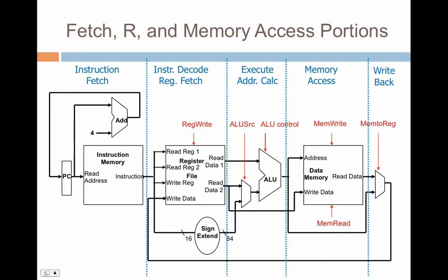the instruction fetch, where we fetch the instruction, then decode and register fetch. We find out what the instruction is so that we can set the control bits, and we fetch data from the register file. We execute in the ALU or calculate the effective address if it is going to be a memory access, or we could also decide whether we should branch or not.